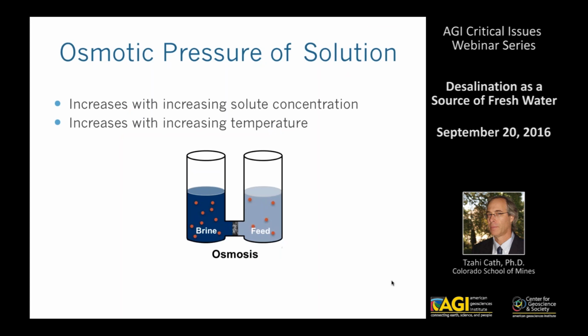And when we do desalination, we use very unique types of membranes, reverse osmosis or nanofiltration, and I'll talk a little bit about the concepts around it. In osmosis or reverse osmosis, practically we are dealing with the natural phenomena of osmosis or diffusion of water from feed that has low salinity into a concentrated brine.